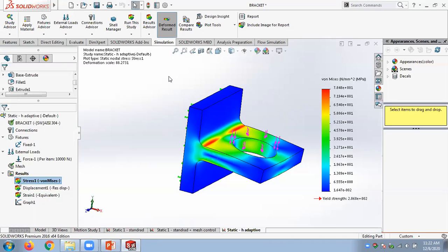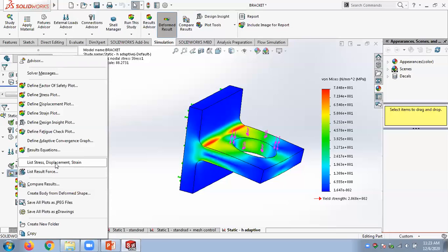So you may think that this is really easy. You can ask the software to do this automatically. Actually, this is somewhat easy. If you have the knowledge of the previous refinement methods, you can ask the software to do this automatically, and then you can expect more accurate results. But you need to know the fundamentals. That's why I taught you the fundamentals in the first few days and started this topic. So this is an automatic tool which will reduce your time. You can right click on this one and get the refine adaptive convergence plot.